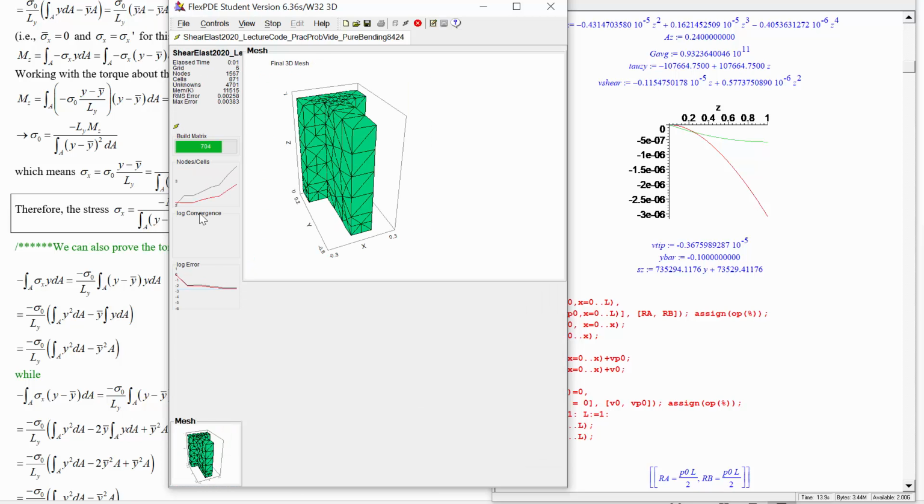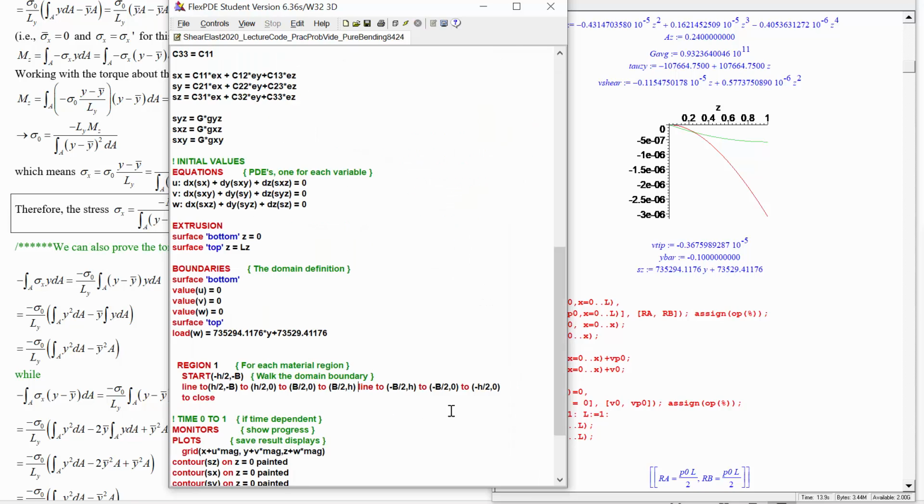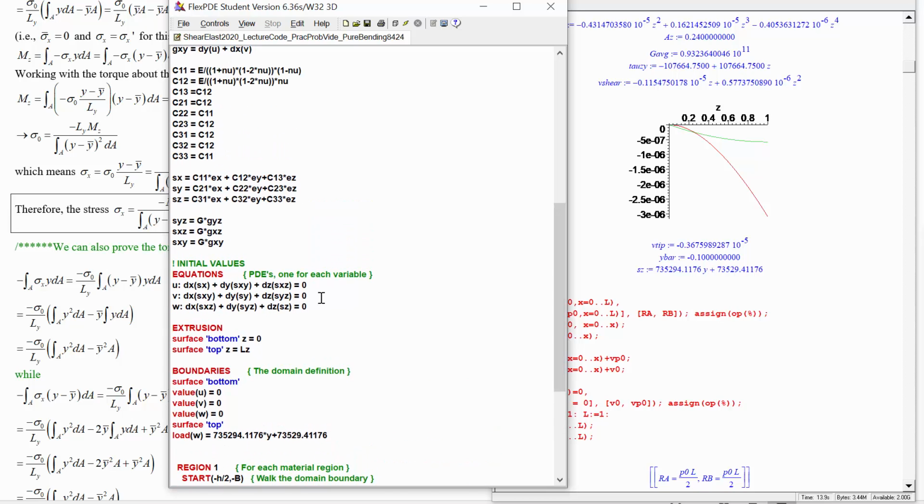And then before this word line, we now can put in a boundary condition, which could be a stress in the negative y direction. But rather than do that, it's also possible to apply this directly as a force in the negative y direction here using the differential equation.